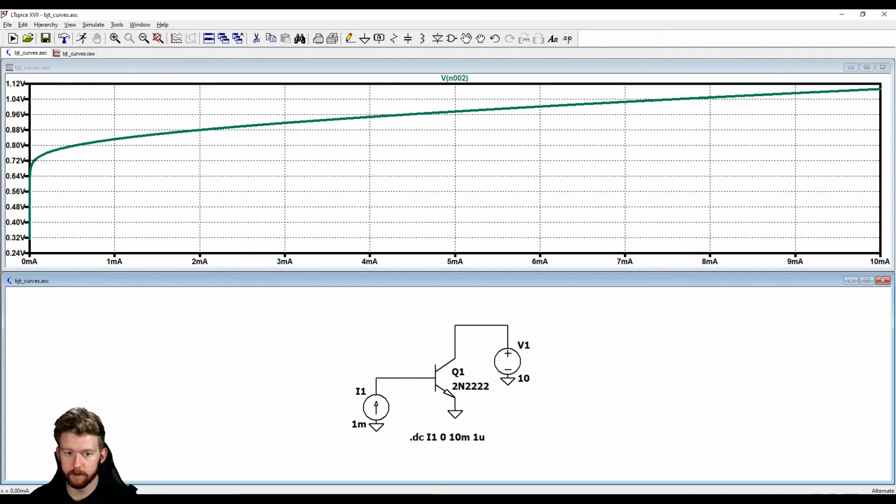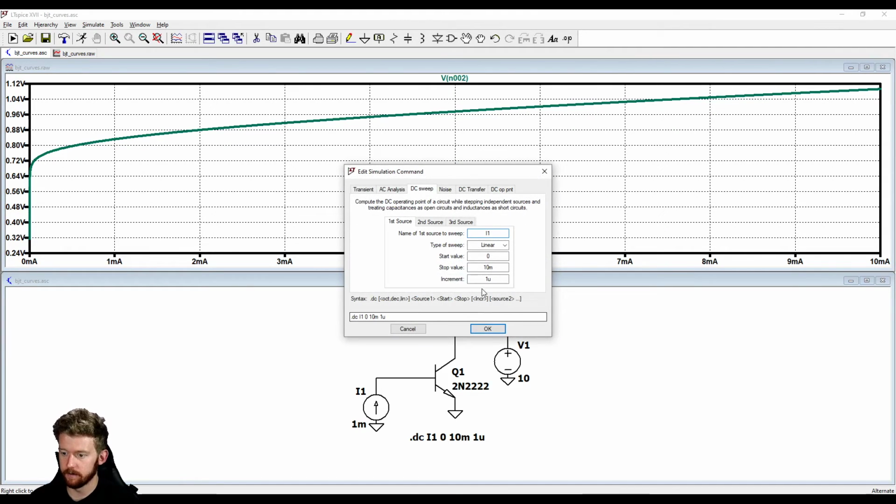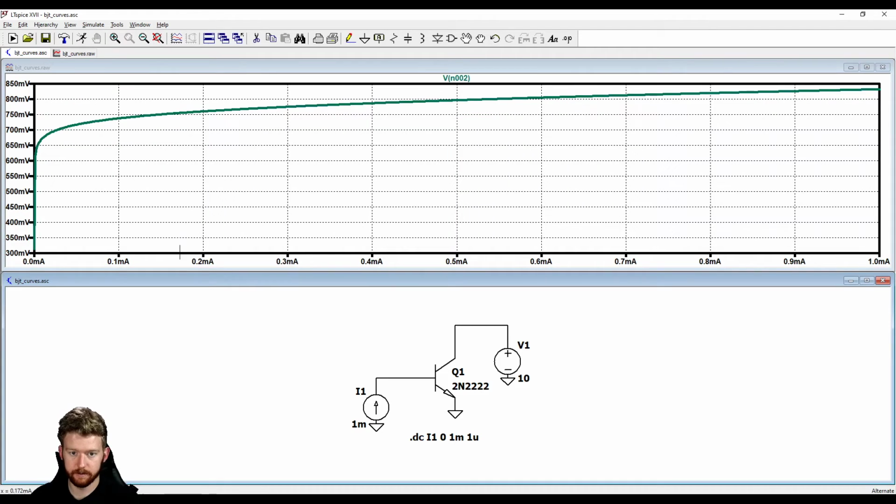So our base voltage, we can see that now it's a whole lot closer to this 0.7 volts that we are used to and that we're designing for. So at 10 milliamps, we're up to about 1.08, 1.1 volts. Okay, so that's still a little bit closer than it was previously. Maybe we can drop this down again. So let's just drop it all the way down to 1 and do another simulation. Okay, so now our voltage is right about at that 0.7 volts. So we're not straying too far away from that 0.7 volts, and this is a little bit more of a realistic case.